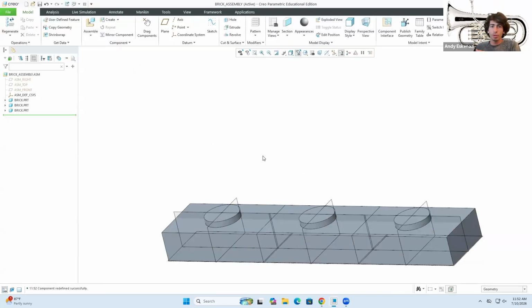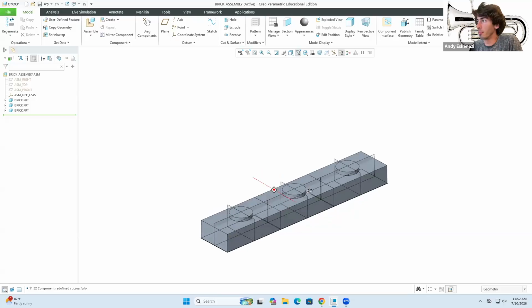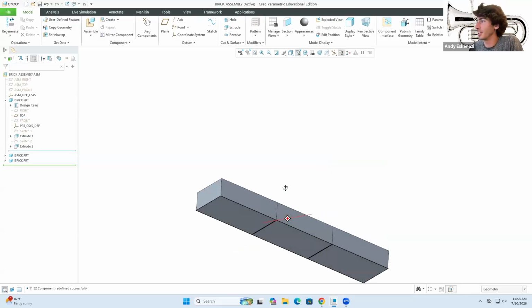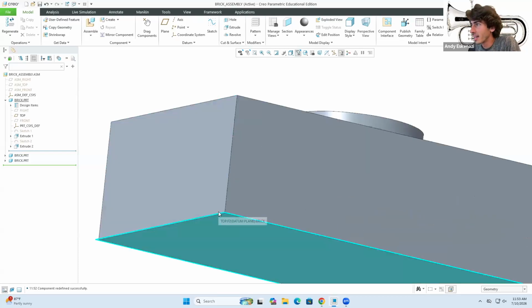As you start to see, we are in 3D. In 3D, there are 3 planes, which means that there's always a minimum of 3 constraints that you have to establish in order to fully define the position of one of these objects, which is why it's always 3 constraints per little part that you have in here. You see, you have all of these planes that are a little bit cumbersome to see. I can hide it in there, and I can hide it in there. You see how these are all the same parts, which means they end up disappearing for all of them.